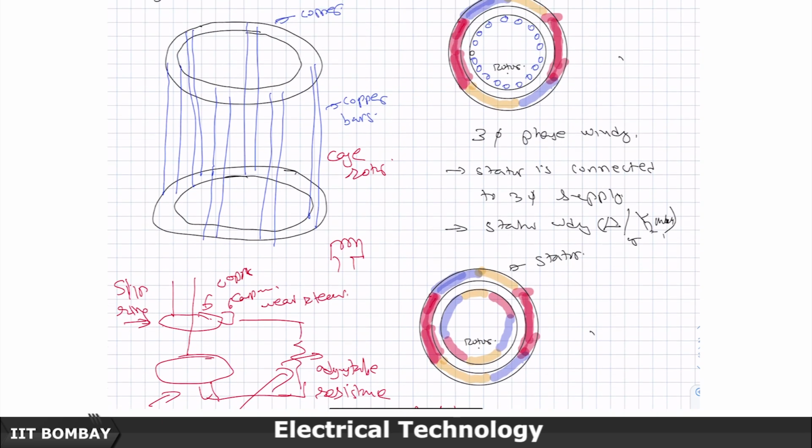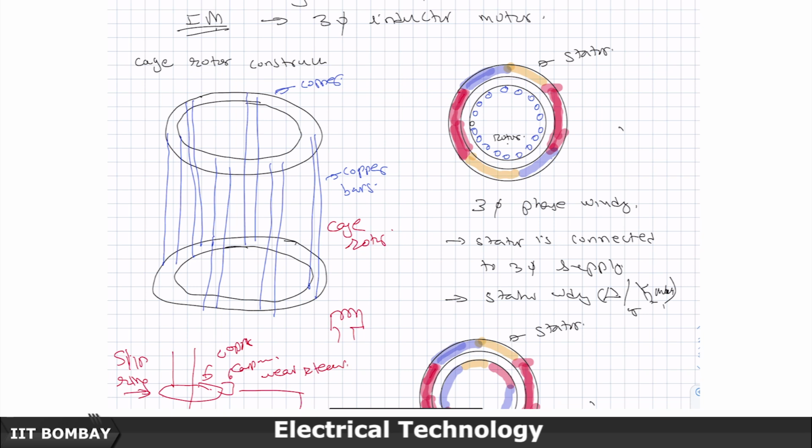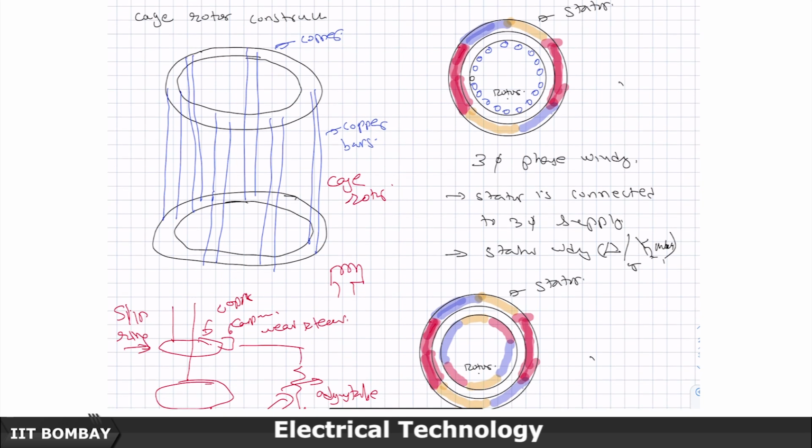But first we will just discuss the induction motor, which is a cage rotor construction. So, you can think of it as if you have a three phase winding. Sometimes I will say that I am having 3-phase winding, properly distributed, just like that on the stator, but which is short circuited for the sake of discussing the physics of the problem, but which is effectively translated into a very simple assembly of a cage rotor, squirrel cage rotor construction, which is as follows.